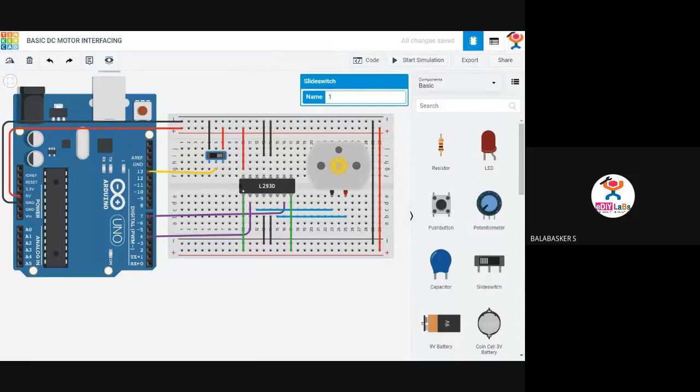After that, we added an ultrasonic sensor. The main thing is, whenever an object comes within that limit, the rays fall on that object and are reflected back, and that is received by the echo pin. If no object is detected, there will be no such value, it will always be above 500, 330. If any object is there, the signal which you sent is retransmitted back, and there will be some variation in the signal. We checked this with a small LED: whenever an object is detected, the LED is on, and whenever there is no object, the LED is off.